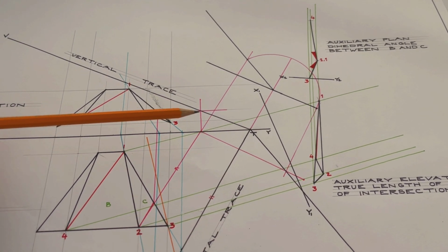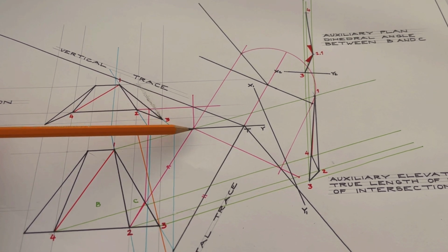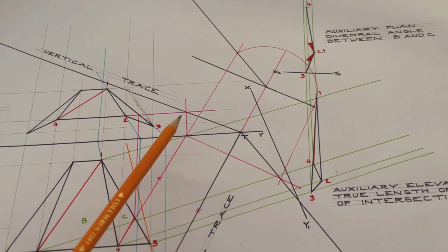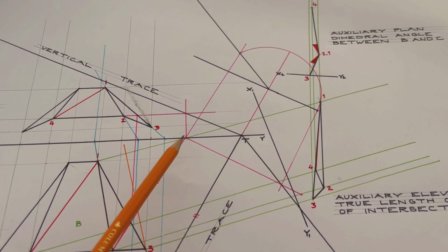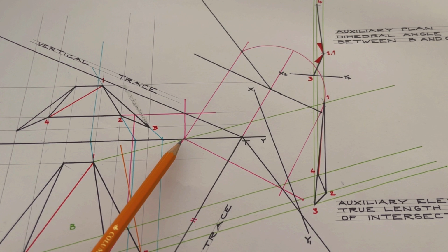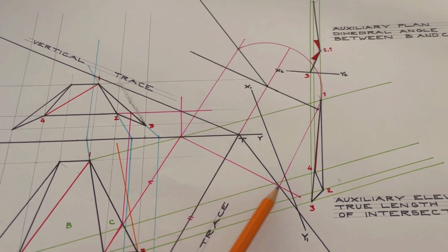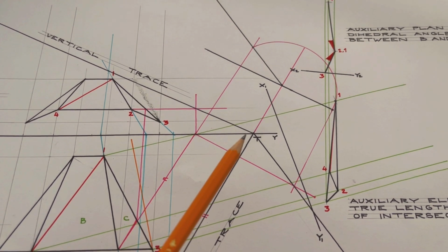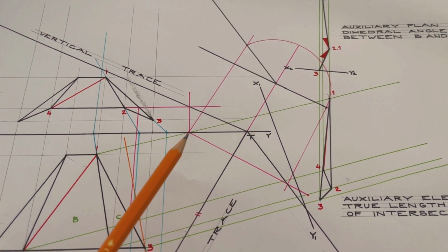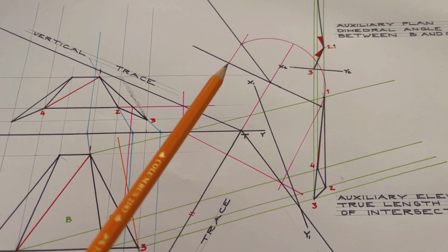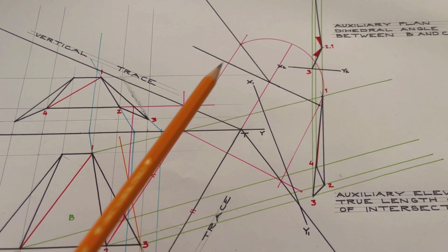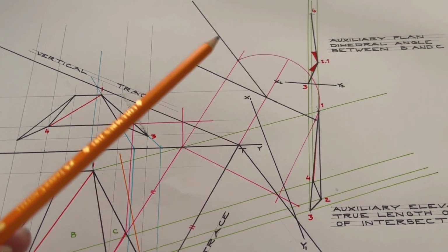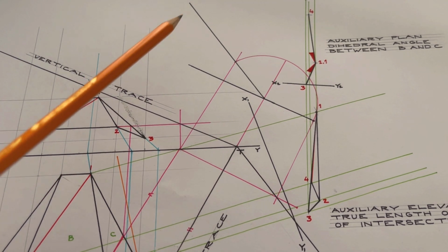We need a known height now on the plane. So here's our height line there in elevation, but that would be the plan of that, because this line is drawn on the vertical plane, because that gives us our point on the vertical trace, which we need over here because we need to draw the vertical trace on the flat. So there's the height line. You bring that up parallel to the horizontal trace. Again, this is an auxiliary elevation, so we take our height here from this elevation and mark it up here. And there's an edge view of the plane that contains C.